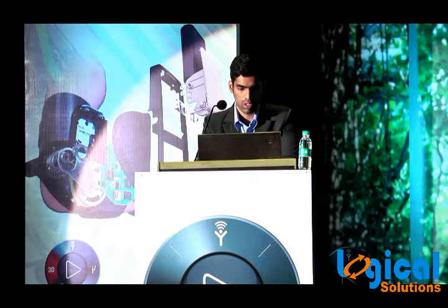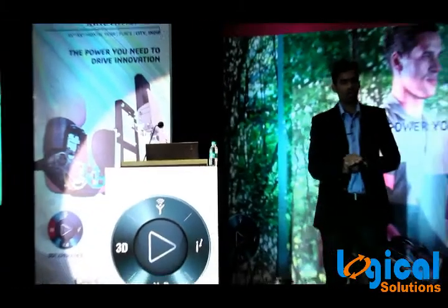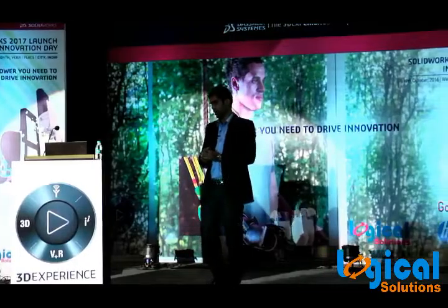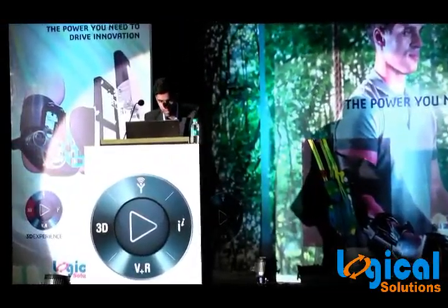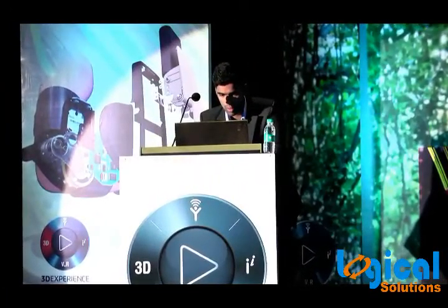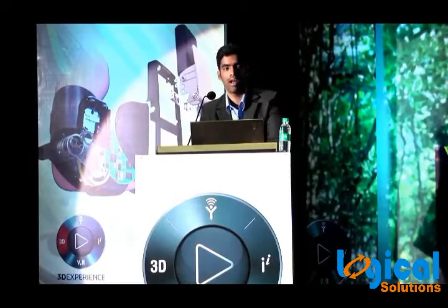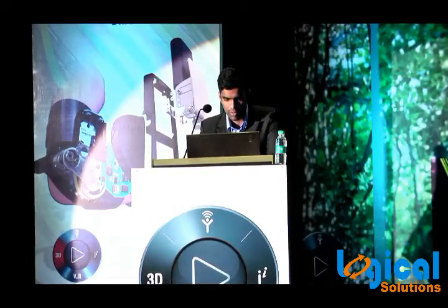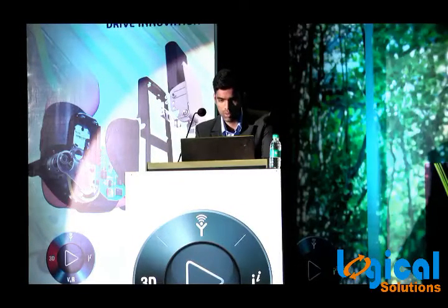As this is a closed contour, you could find a difference, right? Inside that contour we have a different color which is highlighted. So you can drag and drop. Selecting this, you can drag and drop onto the face wherever you want, and after dragging you can add relations and make this a fully defined sketch.